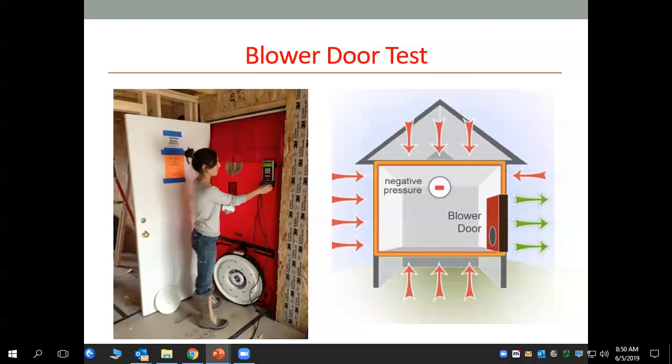One thing that I found in our testing, and again being in the industry, is that if the contractor does not seal the supply and return air boots and the exhaust fans to the ceiling, just putting the grill on and just having the boot tight, it still leaks. So it is very important and can cause failure of the test, or the house to fail. So that's another important piece that sits up there at the top of the ceiling that a lot of times we don't look at, but if you go back, it's a huge factor.